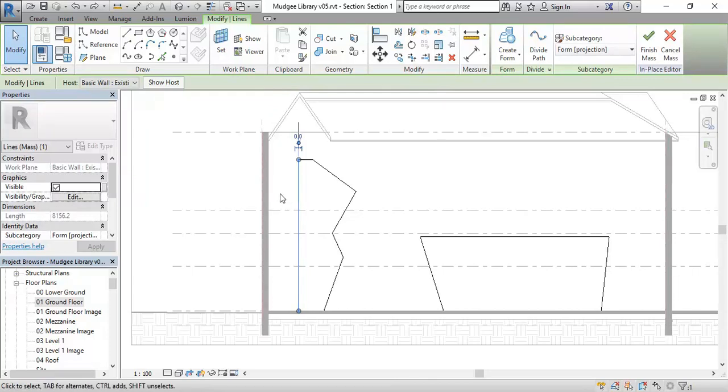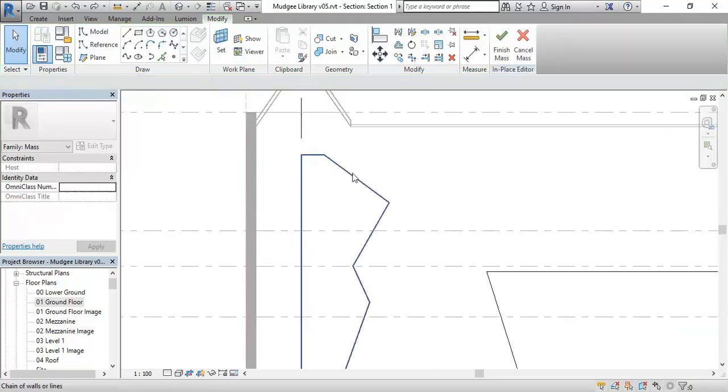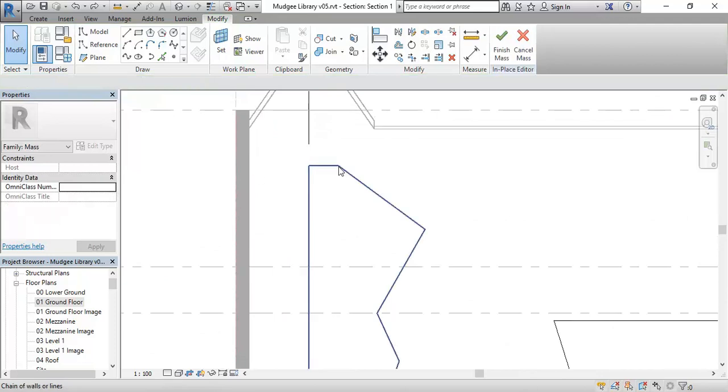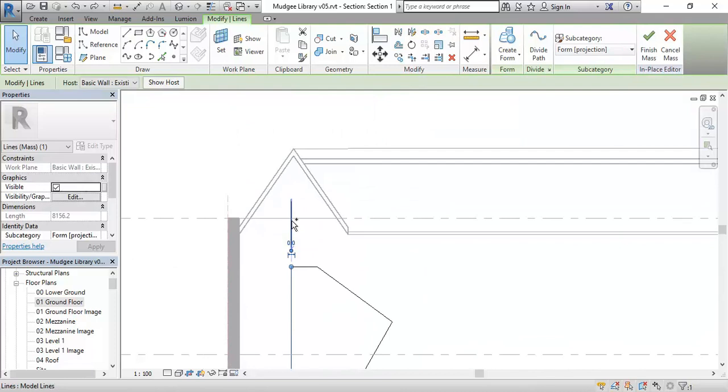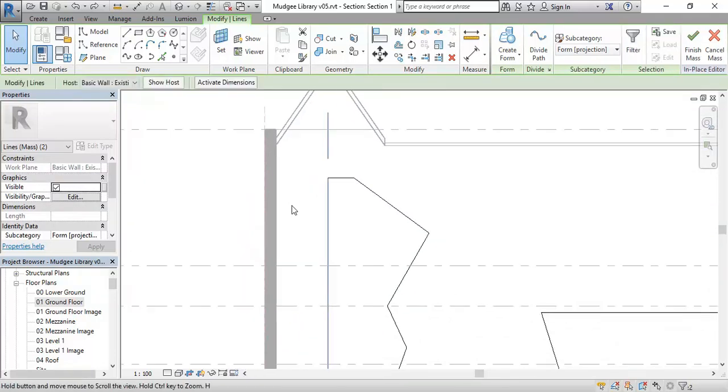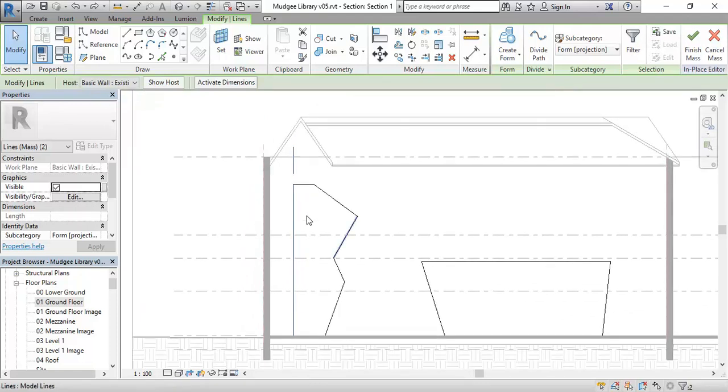So now that was not wide enough. I want that to be bigger. So I've done an undo to go back, and now I'm going to use that method that I mentioned before to select the inner edge. I'm going to select the shape first, and then click on the inside again. So I've got just that edge selected. Now I'm going to select this line at the top with Control, and I'm just going to use the left arrow on the keyboard to nudge those across. I want it to be a bit bigger.